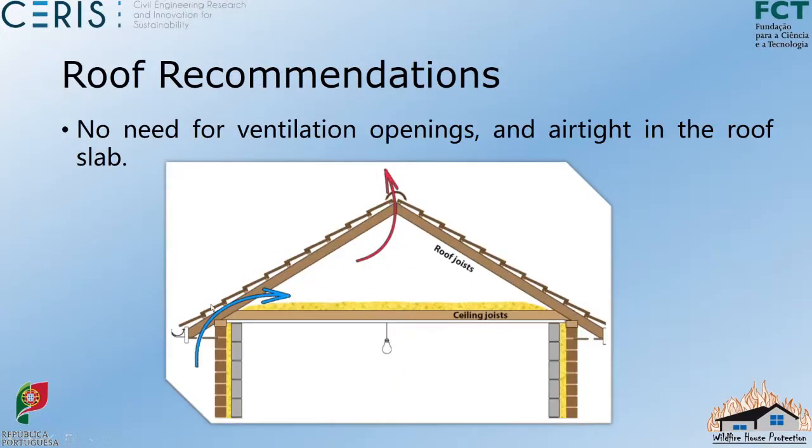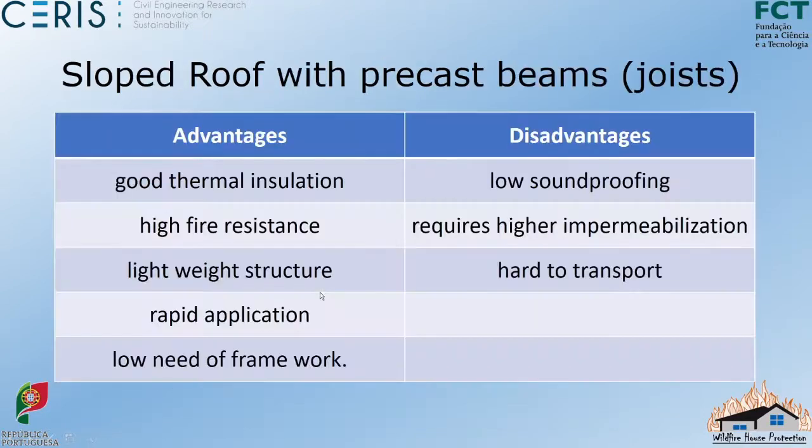Since these openings are not needed, you will not have firebrands entering inside your roof. This is one of the problems of roofs made of wood structure. If you have these openings, I promise you, the firebrands will enter through them. Even if your roof doesn't burn, once firebrands enter the openings, they will get inside your house, and your house will start to burn from the inside just due to firebrand projections. So be very, very careful. And if the firebrands hit some of this wood roof structure, the wood will also start to burn.